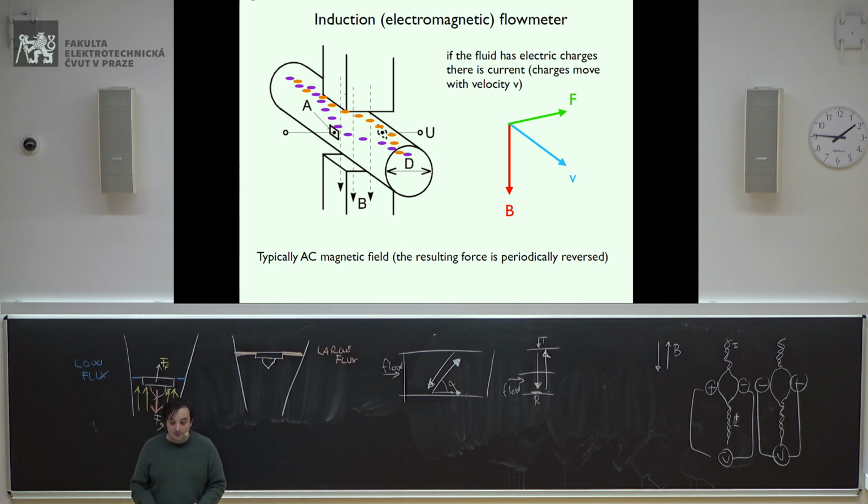If you have 1 kilohertz as carrier of your signal, you know that at the output your signal will be at 1 kilohertz. Whatever you see which is not at 1 kilohertz, then you know automatically is not carrying signal. It's given by something else, by some interference, by some electrochemical reaction in the pipe, whatever. You don't care. You care only about the component at 1 kilohertz, because you know that the output should be at 1 kilohertz.